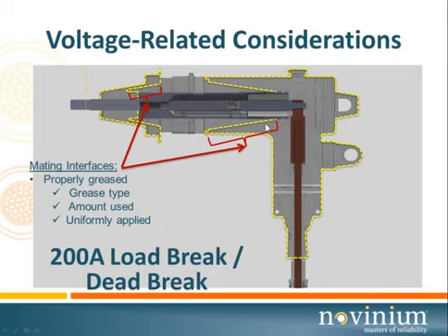Let's take the extremes. Let's assume that your splicer puts absolutely no grease on. He pushes the elbow on. He's a big burly guy. He can get it on, and he will. He certainly won't ever get it off again. That's the first problem. But the second problem is, as he puts it on, this rubber against rubber starts to produce microscopic ripples, just like pushing a rubberized rug across the floor.